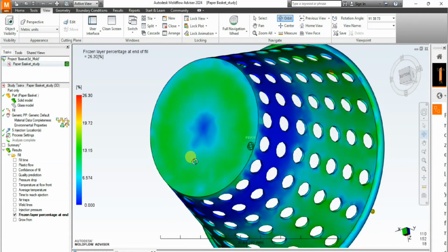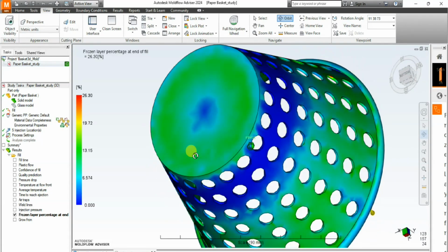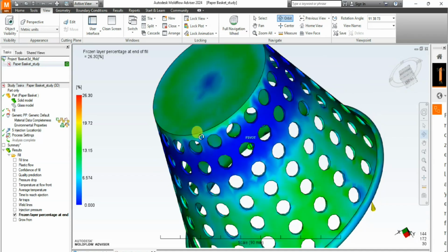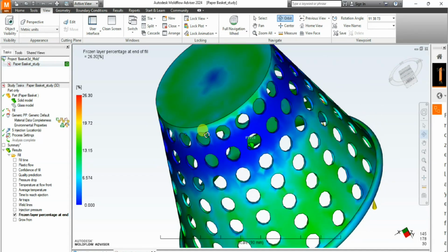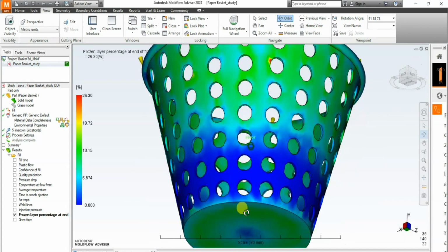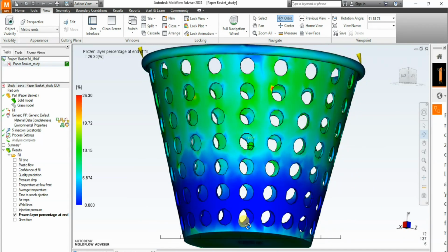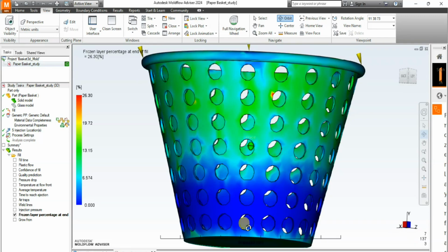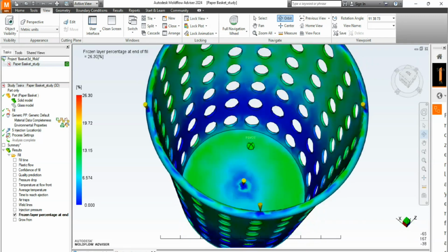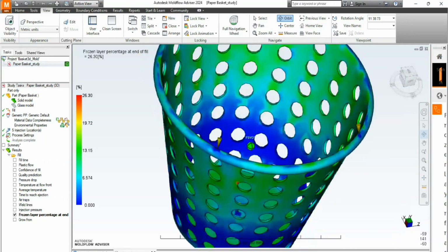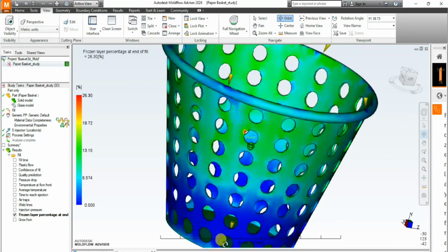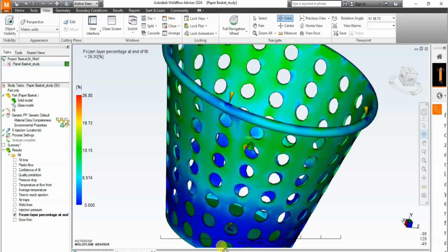That's in this case the waste paper basket thickness. We should also note that a 50% reduction in part thickness reduces the fluidity by a factor of 8, or increases the flow resistance by a factor of 8. This is reminding us of what we learned in physics, action and reaction forces: to every action there is an equal and opposite reaction.